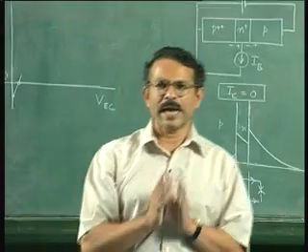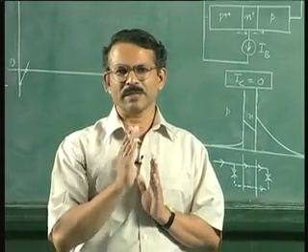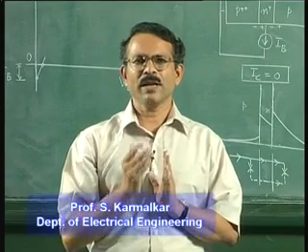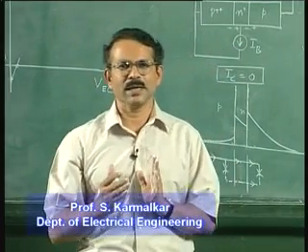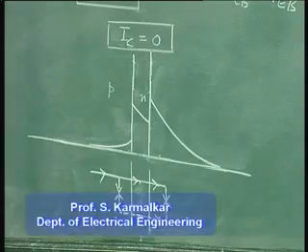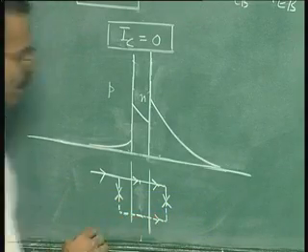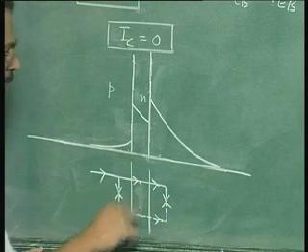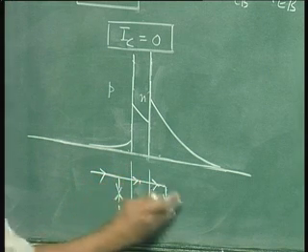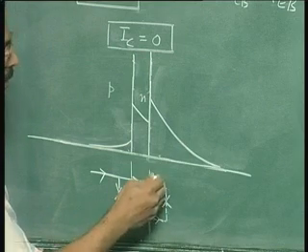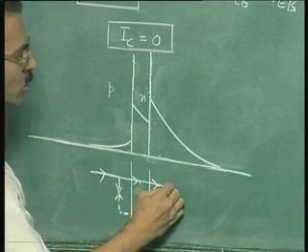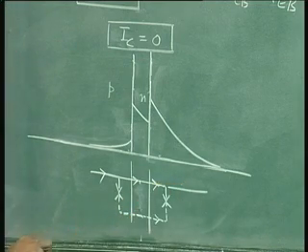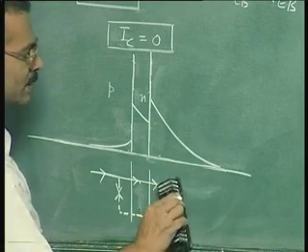If you have holes and electrons both moving in the same direction, then their currents will cancel out if the magnitudes of the hole and electron currents individually are identical. That is the interesting situation here, because of which the collector current is 0. Though you have flow of both holes and electrons, since this flow is in the same direction for both carriers, you can see here that the holes here are recombining with electrons. So there is no current here, right, that we were showing earlier. This is how you get 0 collector current.